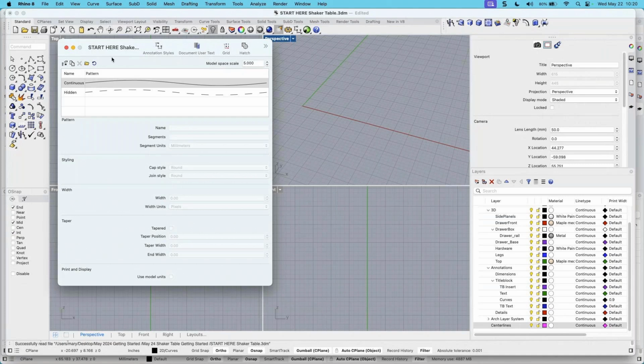One way that you can make a template is to open up a file that you've already done. Let's say it's a building, delete everything. You love the layer system. It's got really good descriptions, colors, line types, materials, and just save it as a template. And then every time you go to do a similar model, let's say a commercial building, you use that template.